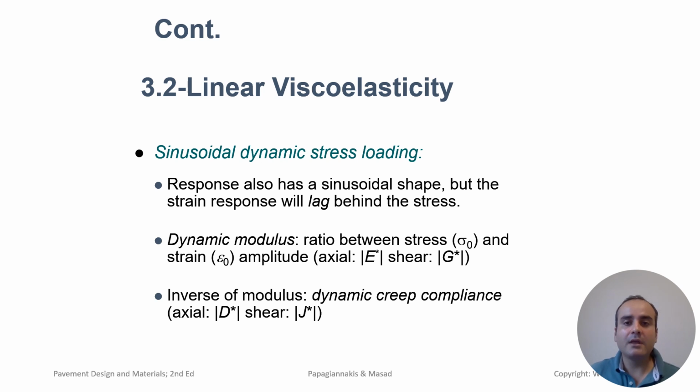Dynamic loading refers to the application of a load that varies over time, in contrast to a static load which remains constant. In the context of asphalt testing, dynamic loads simulate the real-world conditions of traffic loads moving over the pavement repeatedly. The dynamic stress applied during sinusoidal loading helps measure how asphalt materials respond to varying loads at different frequencies and temperatures.